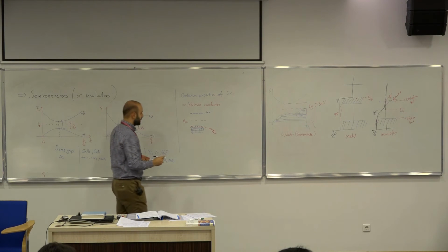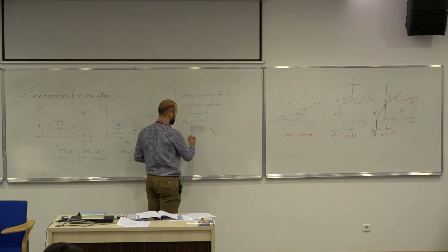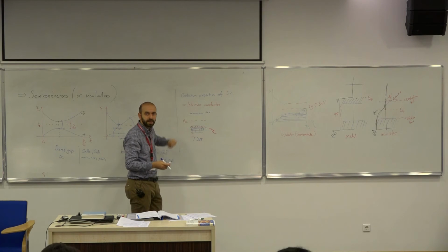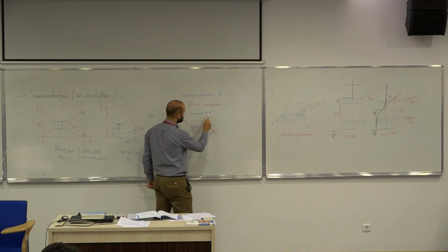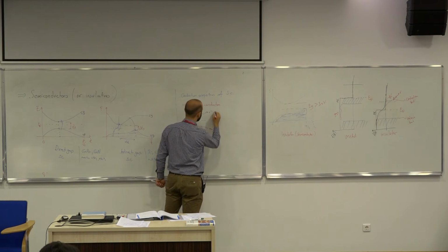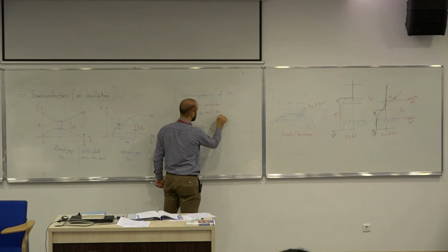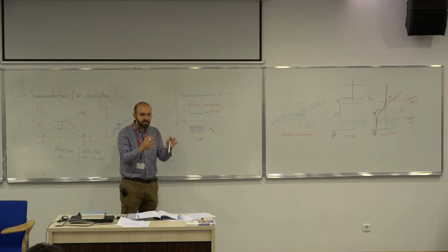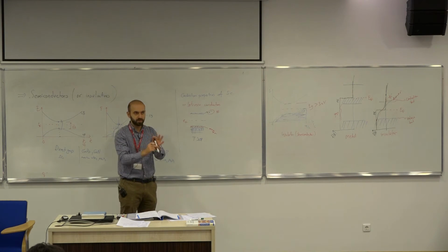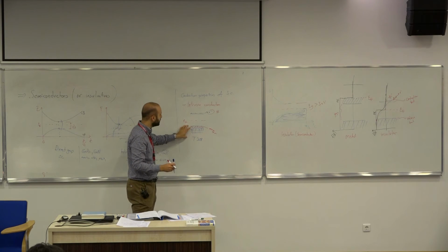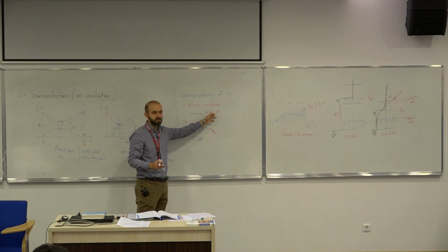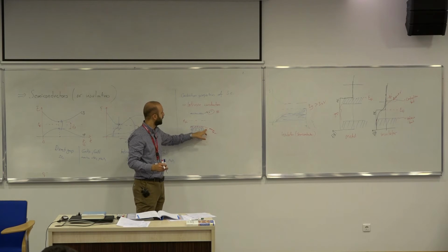So obviously this is at some temperature that's greater than 0 Kelvin, so that I could transfer electrons from here to here. And as you can see, and as I mentioned earlier, the number of electrons is equal to the absence of electrons here, because in this material I have a certain amount of electrons, and I know that these electrons came from the valence band to the conduction band. So if I have n electrons in the conduction band, then I need to have n missing electrons here.